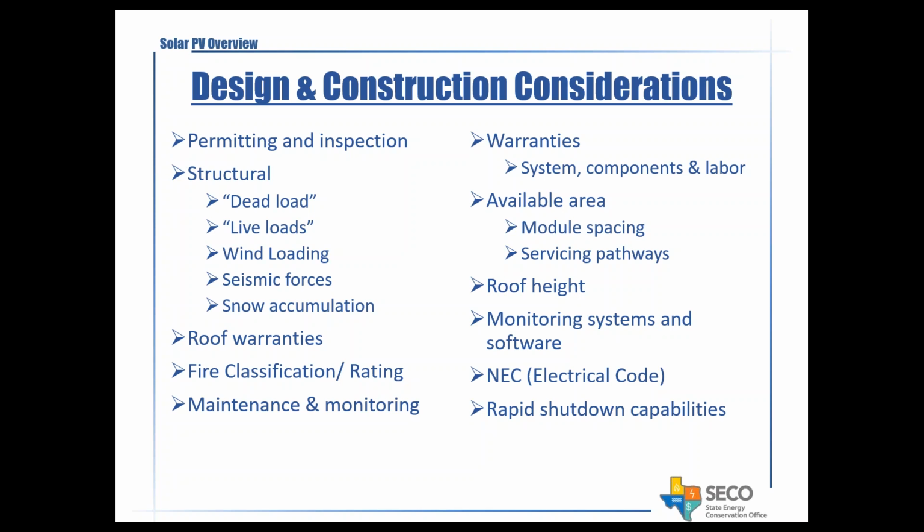Of course, the structural load was discussed basically. There is a structure, you got to be aware of it. Primarily, this is not a very complicated analysis, but something you just need to be aware of. The roof warranties, as Joey mentioned earlier, have to be taken into account, and anything you do on the roof, you just want to make sure that whoever has the warranty is aware of it and is involved in the process, basically.